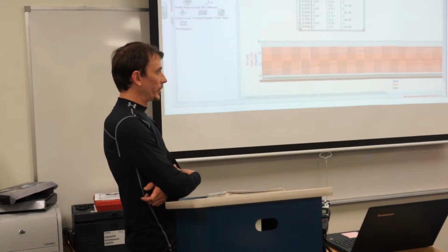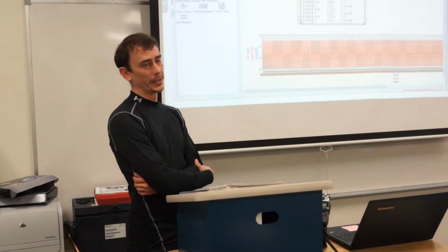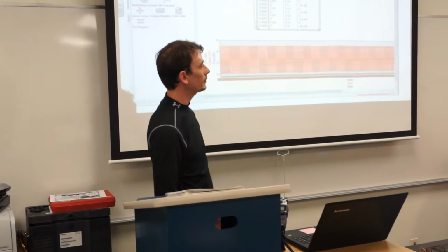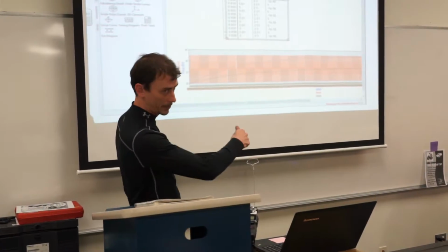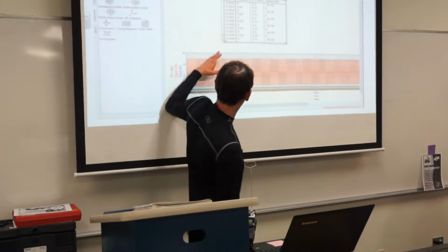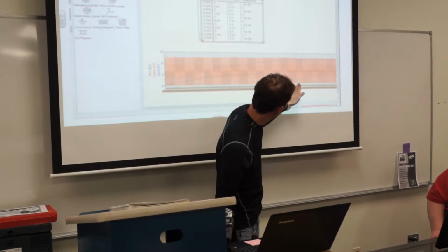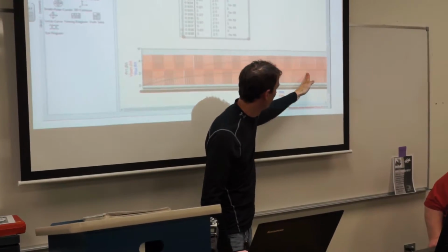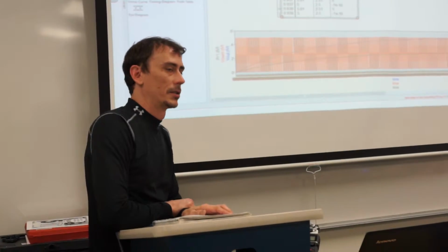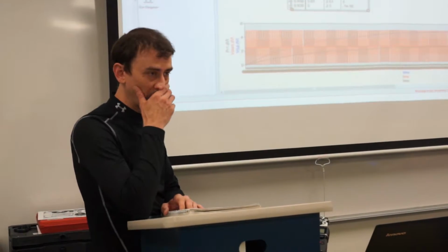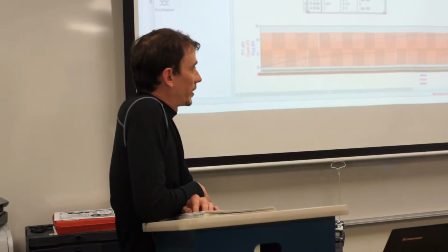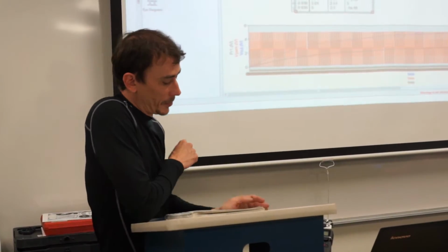I gave a design goal of 0.6 seconds to reach desired voltage output. This graph is showing, again, we're at our 50% voltage request, where we've got the knob turned up halfway essentially. So if this is 5, here's our 2.5. You can see it takes about 0.6 seconds, which is happening right out in here. I felt that was about the limit for what I wanted to see. I didn't want it to take 5 seconds for the voltage to get to where you wanted it, and that's probably a little annoying no matter what device you're trying to power off of it. But by compromising there, you do get a much smoother voltage.